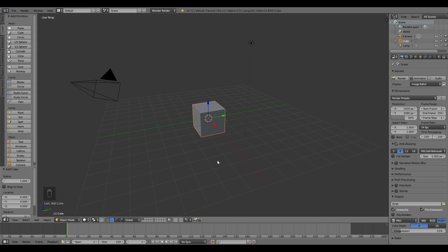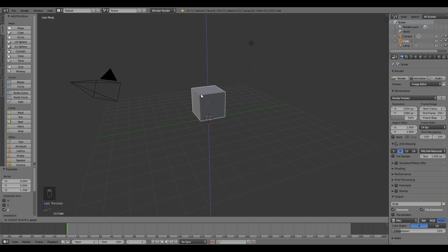Before we do anything, I want you to left click down on the cube. If you haven't already selected it, right click, it's selected if there's a yellow border around the cube. Drag it up on the Z-axis, which is the blue line, with the left click button, and just drag it up until it's not going through the ground anymore. Alright, now that that's done, left click down on the green arrow, drag it to the left.